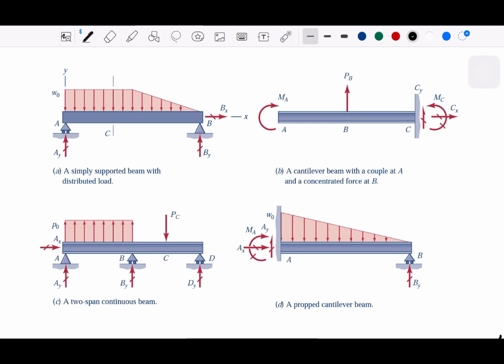First they have a roller support, and this is just a fixed support. Because it has a roller, it can move freely on this axis, right? So we are just going to see one reaction force. For this one, we have y-axis and x-axis reactions. So based on the support, we can distinguish how the reaction force will be.